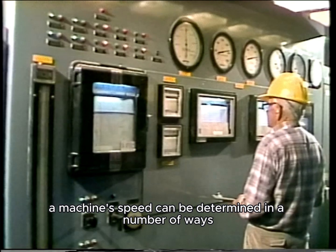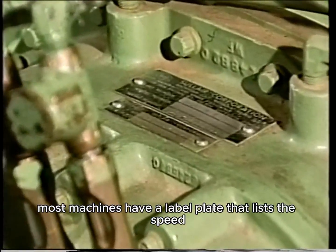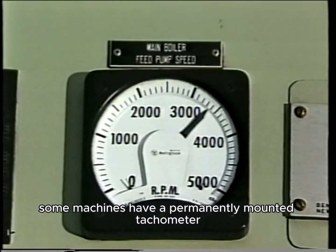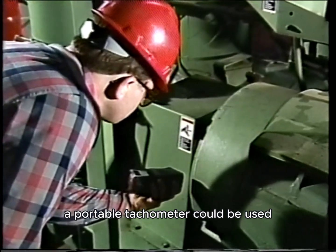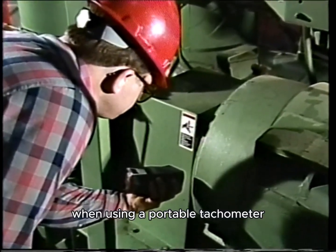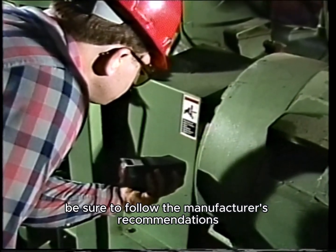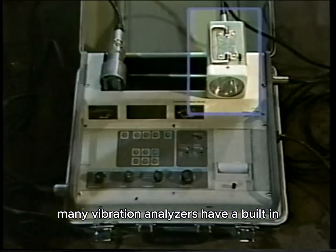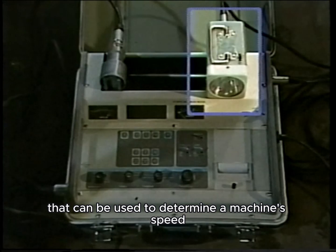A machine's speed can be determined in a number of ways. For example, most machines have a label plate that lists the speed. Some machines have a permanently mounted tachometer, others do not. In this case, a portable tachometer could be used. When using a portable tachometer, be sure to follow the manufacturer's recommendations for that particular unit. Many vibration analyzers have a built-in strobe-type tachometer that can be used to determine a machine's speed.